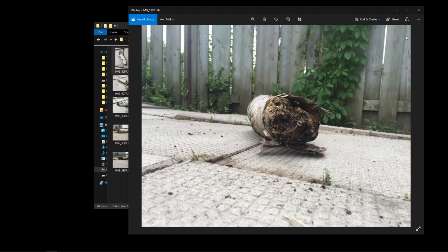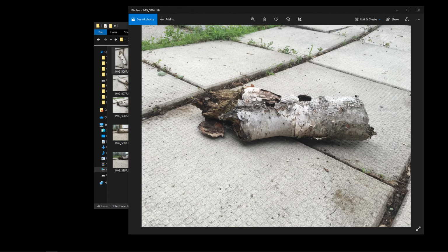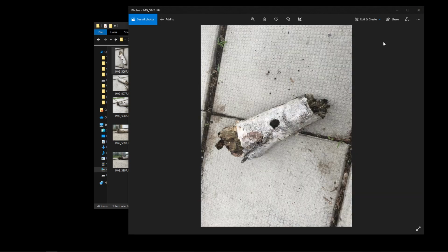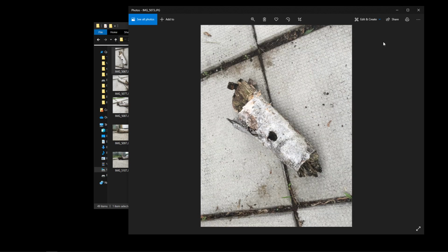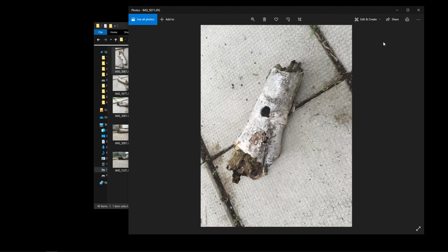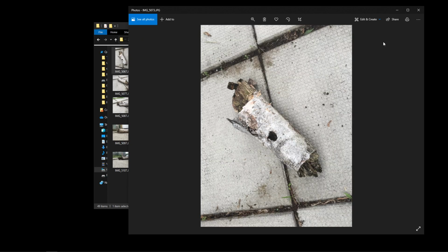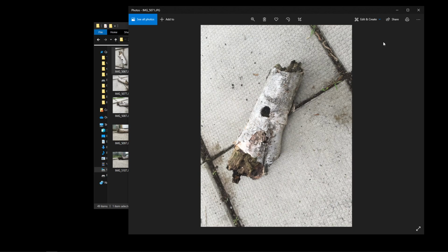In terms of how to decide how to take these photos, what I found worked fairly well is to start with a couple images around the top of the object. So you can see fairly high camera angle here. I'm almost looking directly down on top of the asset. Of course, we don't need as many photos from this angle because we can basically see most of the object from every angle. This is just to contextualize the main texture. That photo information for the texture itself, just get a nice view of that from the top.